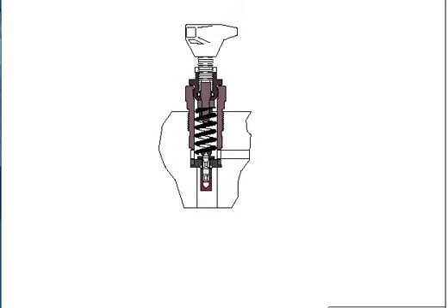A direct-acting relief valve is one in which the poppet is held closed by direct force of a mechanical spring, which is usually adjustable. Spring tension is set on the knob to keep the poppet closed until system pressure working against the poppet reaches the desired cracking pressure. When the system pressure reaches full relief value, all fluid is passed across the poppet to the tank passage.